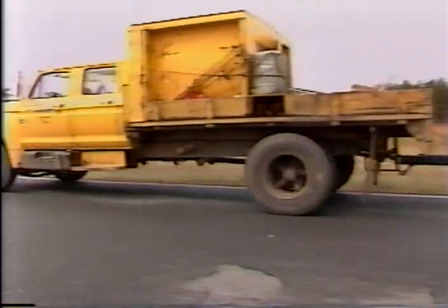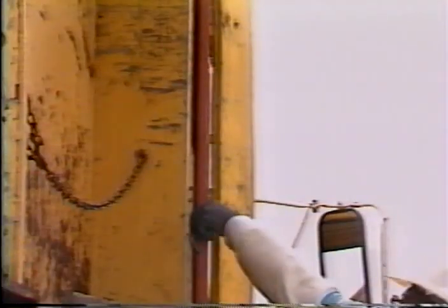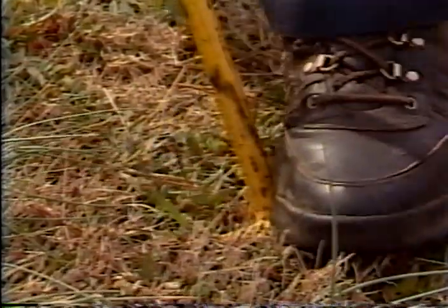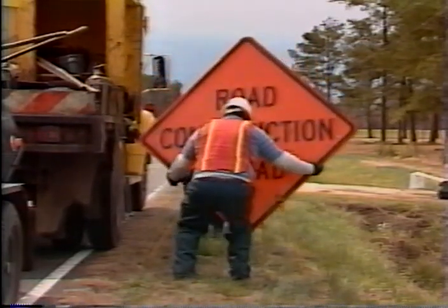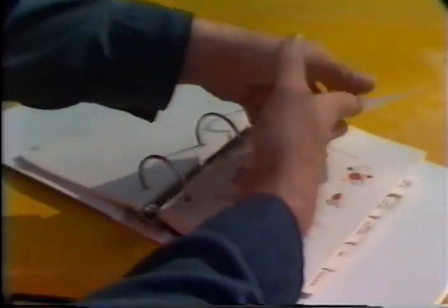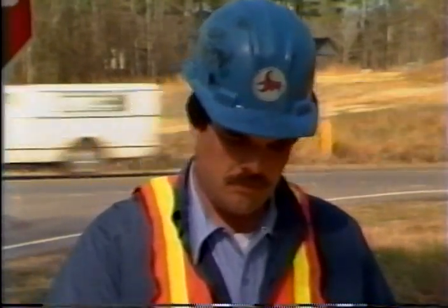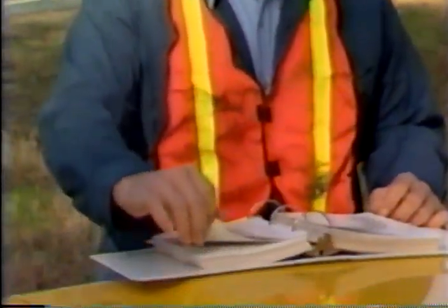Proper worksite traffic control is necessary for the safety of the work crew and the traveling public. Also, there is legal liability on the governmental agency to use established traffic control measures. Never begin repair operations until proper traffic control measures are in place. Proper traffic control begins with a plan. The supervisor consults the MUTCD or other appropriate work zone traffic control standards to determine the proper traffic control needs for the given situation.